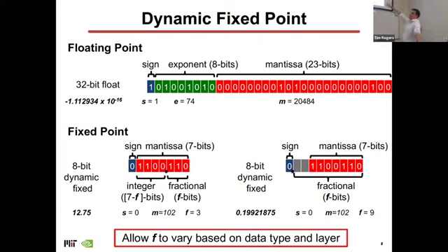Let me just give you the actual numbers. You've got 5 bits for the integer part and then 3 bits for the fractional part, and then I can reconfigure it to interpret this as another number. Well, it's not 7 bits because you have a sign bit there if it's signed fixed point, where I basically have all fractional bits. So you could on the fly change where the fixed point is.